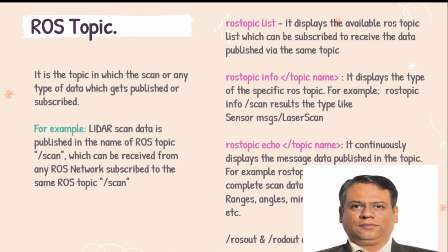For example, here the Lidar is already scanning the data around the environment. It is rotating through 360 degrees, right? For each and every degree, there is some distance. For example, here I am, and on this degree the laptop is in front of me, so it may be at a distance of 5 centimeters. So on the 0th degree and the 360th degree, there is 5 centimeters.